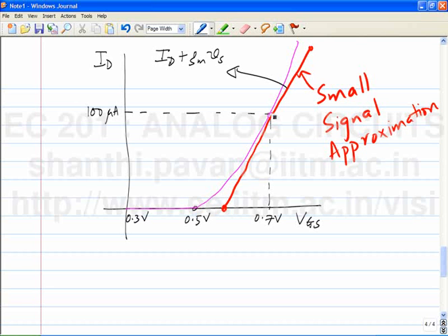We have linearized about this operating point here. Then we have drawn this straight line, and from the straight line, we have surmised that the transistor will get cut off provided the small signal amplitude is this value.